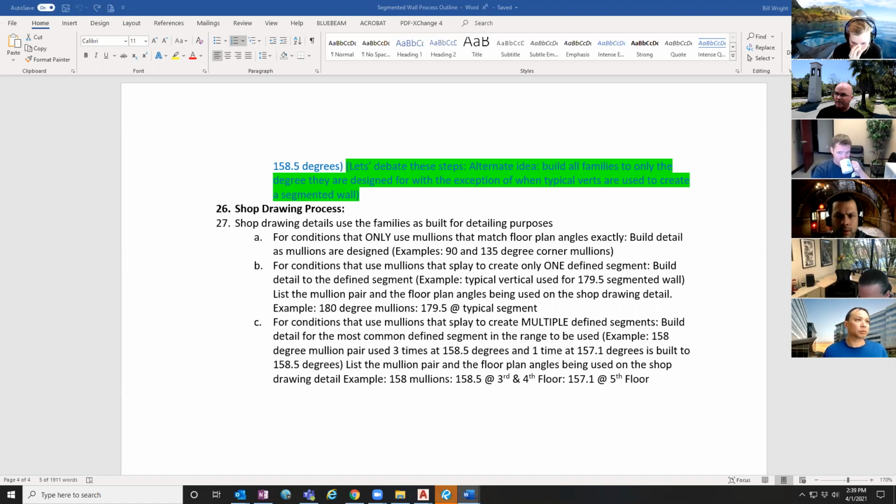So pre-bid, Jumpstart should be figuring out the mullion pairs, drawing the bond widths, etc., to see if we need any new dies, because pre-bid's the only time we can get money for it. Then post-bid, we need to do a floor plan layout and try to minimize the angularity on the floor plan as much as possible with discussions with the customer.